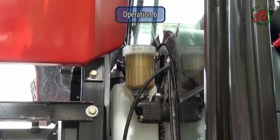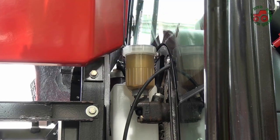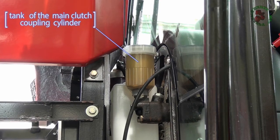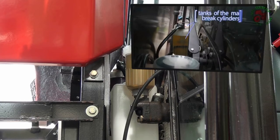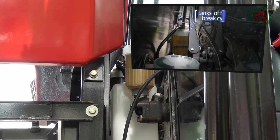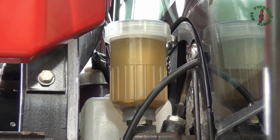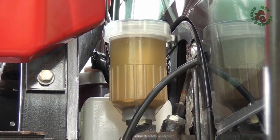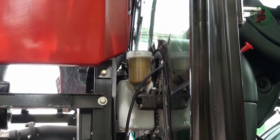Operation 6. Check hydraulic brake fluid level in tanks of hydraulic drive clutch and brakes operation control. Check visually hydraulic brake fluid level in the tank of the main clutch coupling cylinder on the left side along the tractor above the hydraulic system oil tank, and tanks of the main brake cylinders on the right side above hydraulic steering control tank. Level shall be between minimum and maximum marks made on the tank's housing. If necessary, add the hydraulic brake fluid up to the maximum mark, having turned off the tank caps.